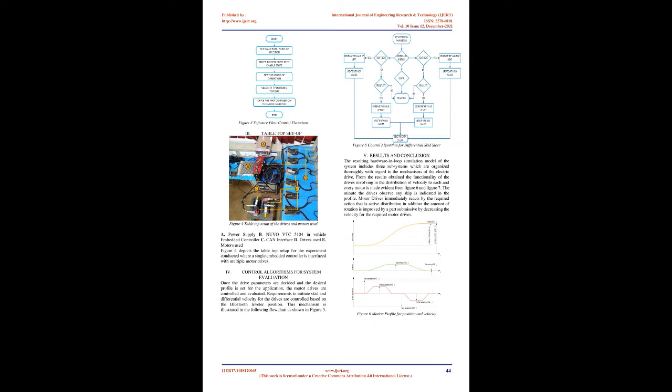CANopen is a higher layer protocol based on CiA, providing flexibility to configure a wide range of applications. Table 1: CANopen frame. Function code, node ID, RTR, data length, data. 4-bit, 7-bit, 1-bit, 4-bit, 64-bit.